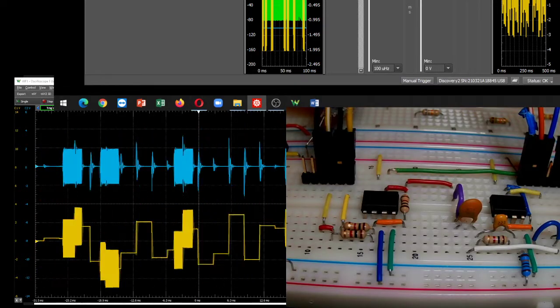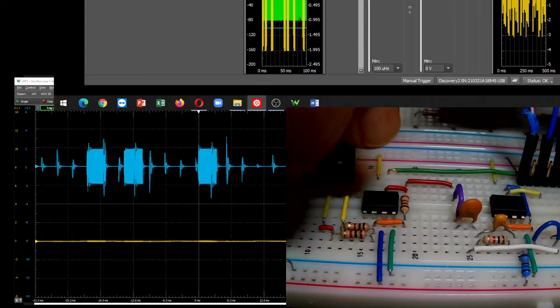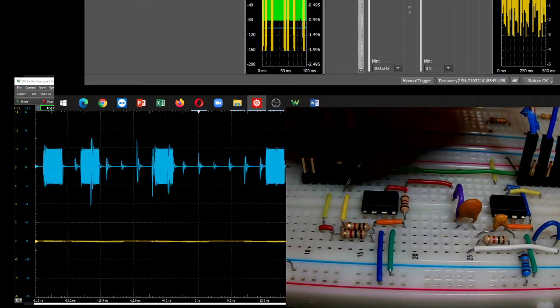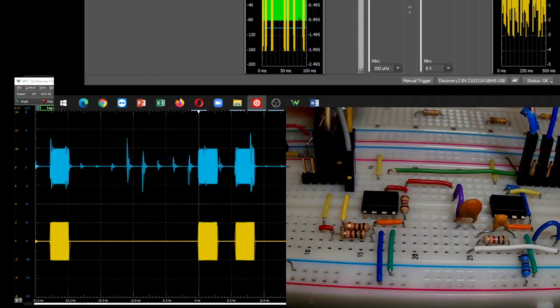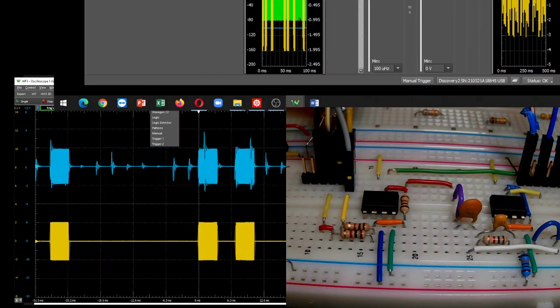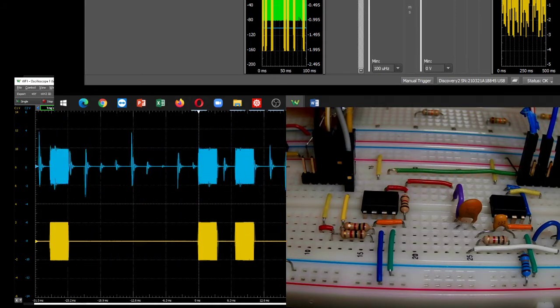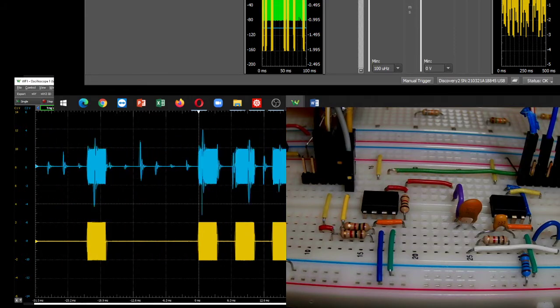In the following, the original AM signal, yellow, bottom, can be compared with the output from the high-pass filter circuit, blue, top. Certainly, some noise leaks through, as there is no such thing as a perfect filter. But this must be viewed within the context of how large the noise is. Also, the filtering is not complete. There is still a later filter stage that can reduce the spiky noise.